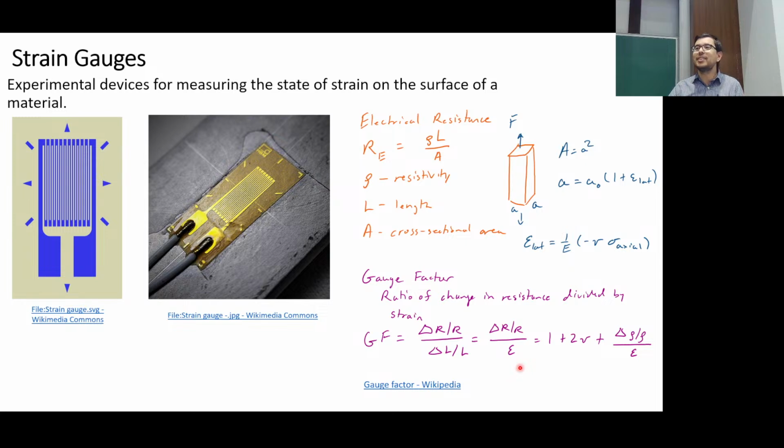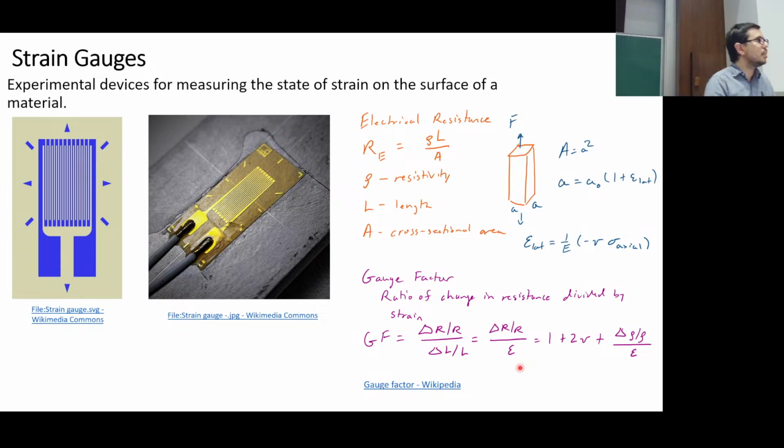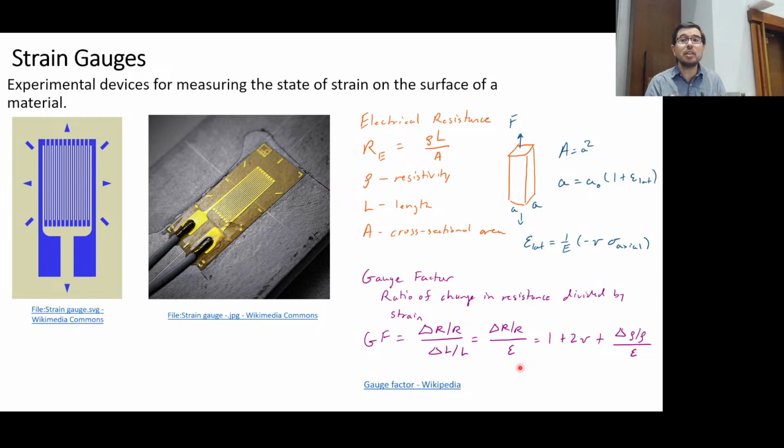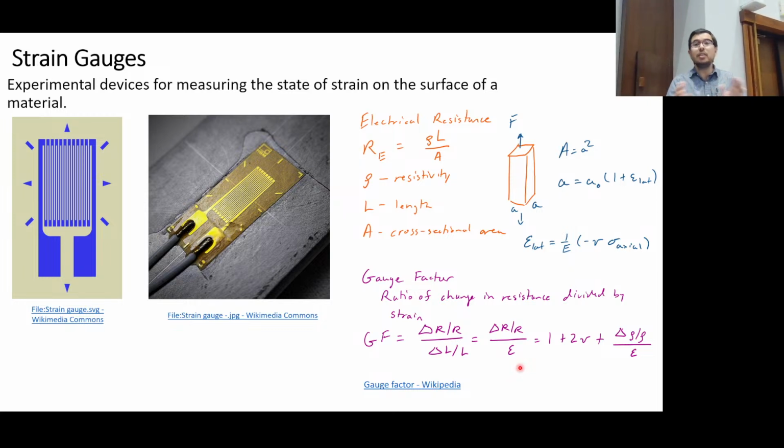Someone I know, yes. V equals IR, right? So what you're typically doing with these devices is measuring: I apply a voltage or a current, and I'm trying to figure out what the R is and how that R changes as I apply some strain. In the measurements class, you'll get to build what's called a Wheatstone bridge, and you'll be able to measure that resistance. Because it actually turns out it's a small change in resistance, since these are small strains.